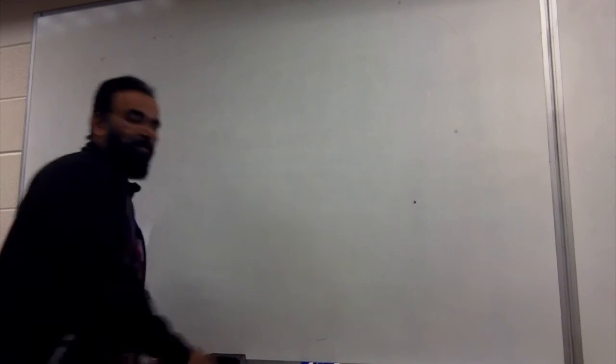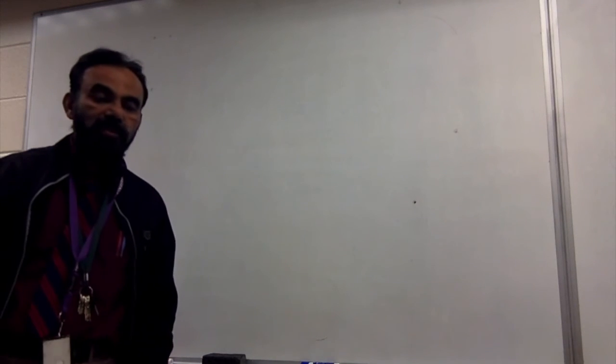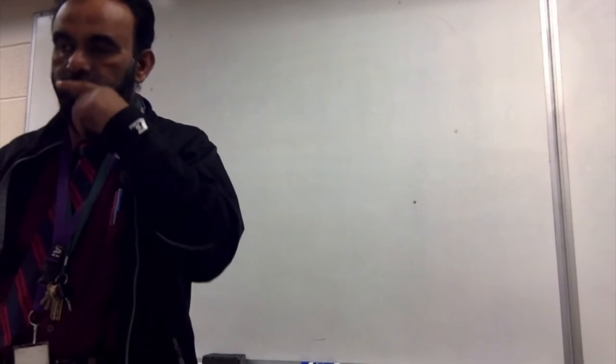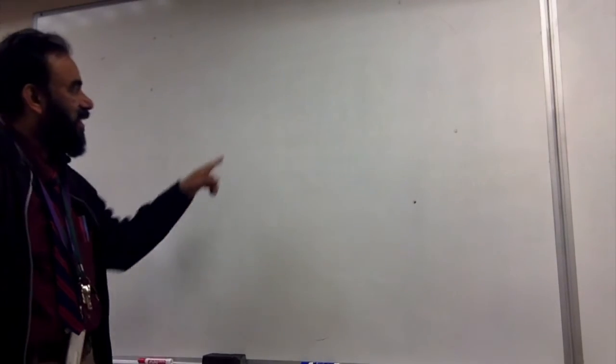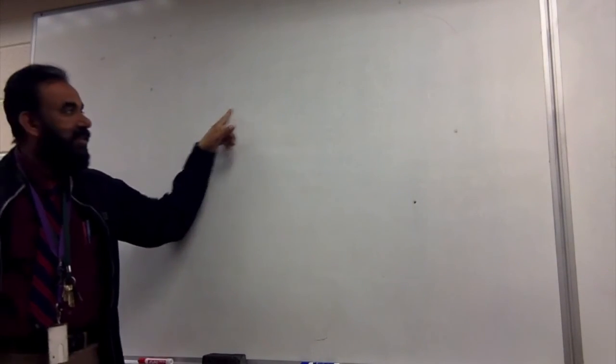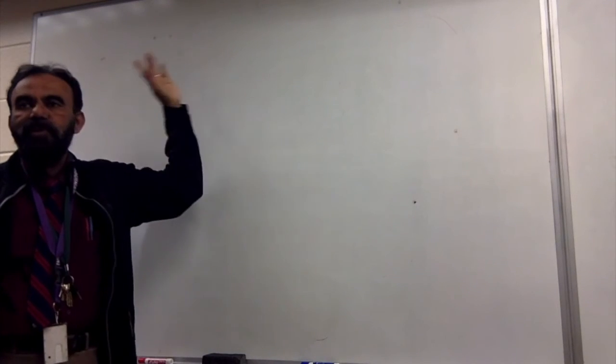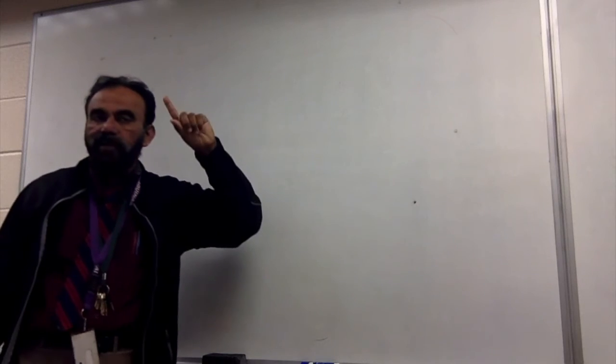If the circuit is more complicated, that's when you use Kirchhoff's laws. You should go back and find out more about Kirchhoff's laws. The first law is that at a point all the currents add up to 0. Like in the previous example, 2 amperes coming from here, 1.5 goes this way, so it has to be 0.5 going the other way. Right? That is according to Kirchhoff's first law.